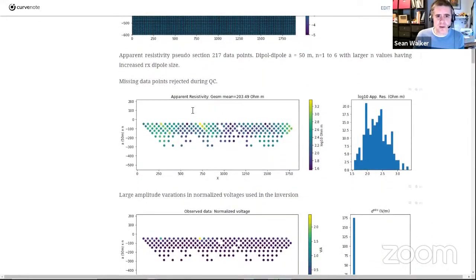Yeah, and then we get down to our data. So resistivity data is commonly presented as an apparent resistivity, which is a nice way of presenting it. Of course, it makes assumptions when you calculate this value, but essentially you get a point, and these pseudo depths are just related to your dipole spacing. As the dipoles get further apart, the plot point goes deeper and plots in between. So these aren't real depths, but it's just a way of visualizing it.